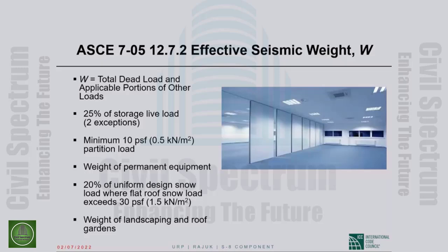Okay, so in storage facilities, we typically include a portion of the design live load in the seismic weight, and so on and so forth. So the point is the seismic weight is not the same as weight, and ASCE 7-05 defines it very specifically in this section. So does BNBC, but the definitions are different, as I'll show you.